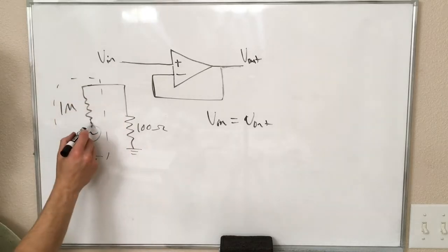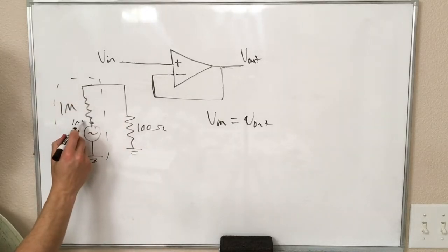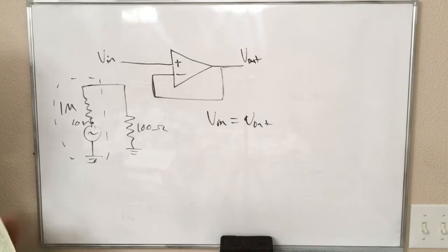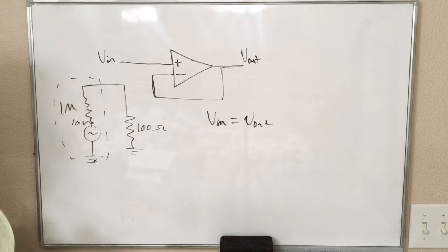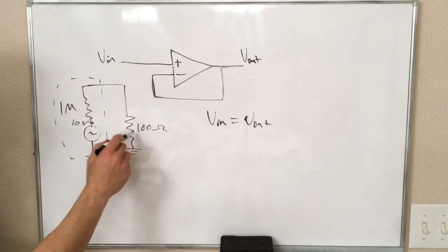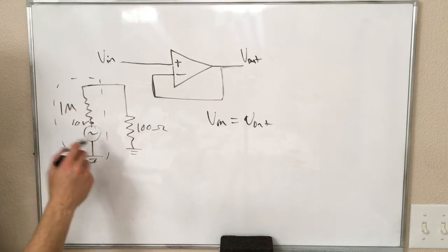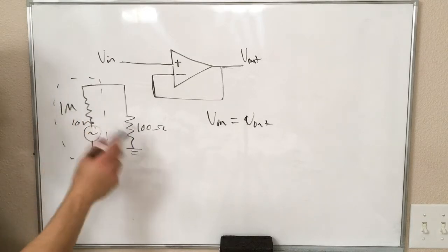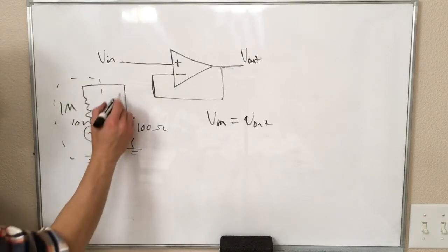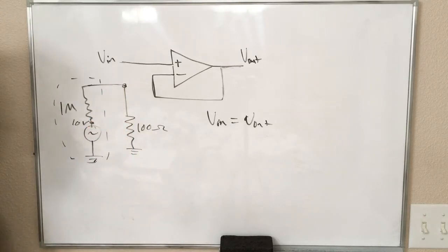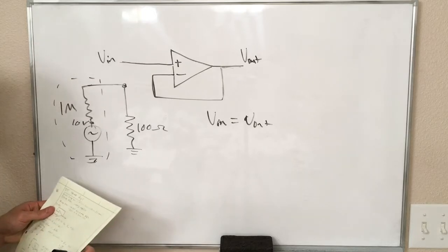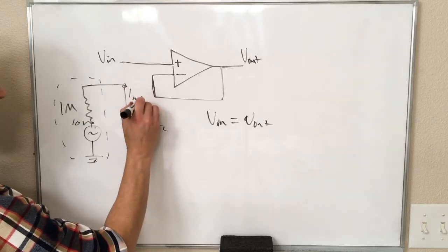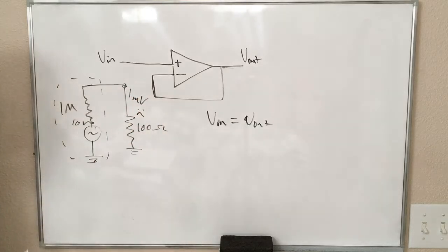If you try to do this, whatever output you have here, let's say 10 volts, you have 10 volts trying to be supplied by your circuit, and 10 volts you would measure if there was no load attached here. But when you have 100 ohms in series with your 1 mega ohm, that's a factor of 10 to the fourth. So at this point, instead of measuring 10 volts, you're going to measure something like 1 millivolt. So that is bad, right?